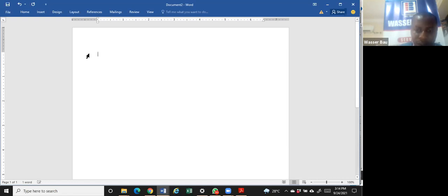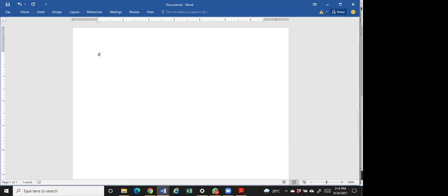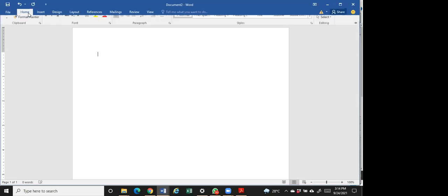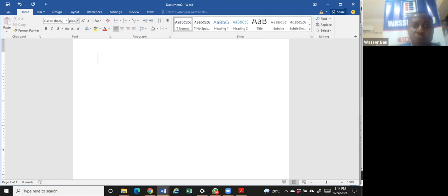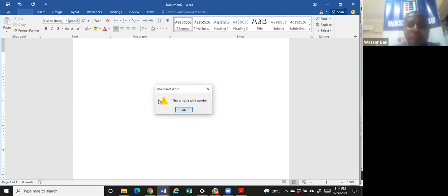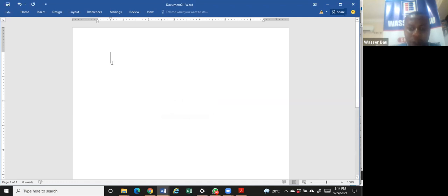Hope you can see my screen. So you need 2 pipe parameters. And for the pipe, what are those 2 parameters you need? They are the elevation. No, sorry, the length of the pipe and the diameter of the pipe. So your table must show the length of each pipe or each section, and it must show the diameter of those pipes. Even while you're detailing your work, you should also follow the same convention.